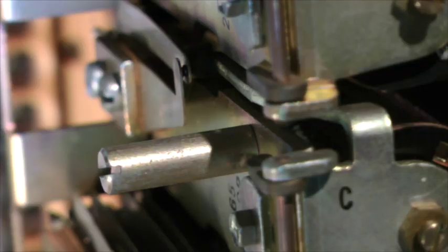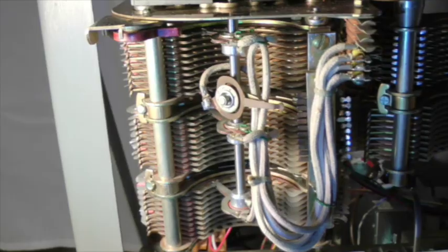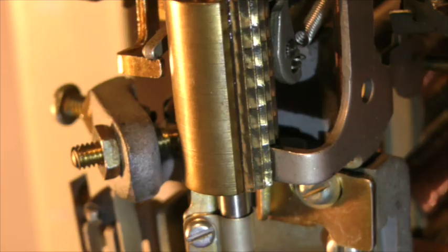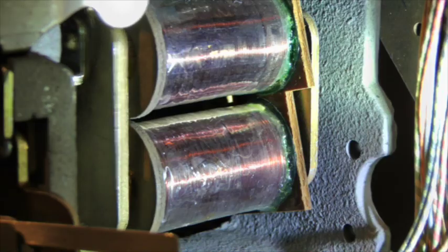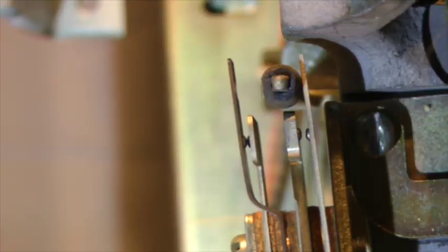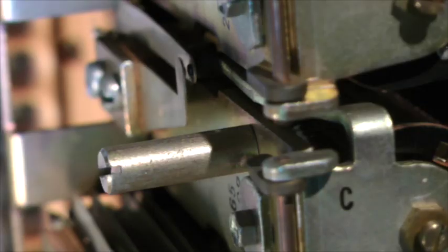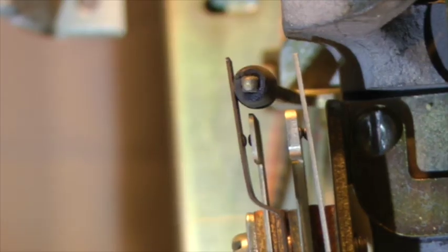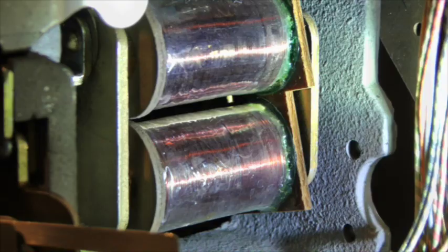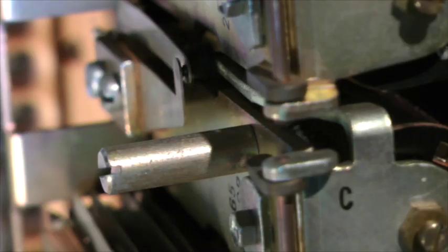The line finder has many electromechanical parts that are identical to those found in selectors and connectors. However, its operational functionality is different. Selectors and connectors are called numeric switches because part of their activity is in response to the reception of numeric or dial pulses. They are seized by a preceding circuit and connect that circuit through to a succeeding circuit.